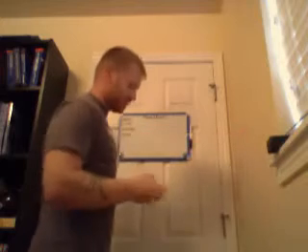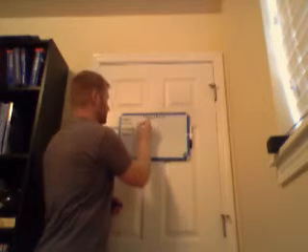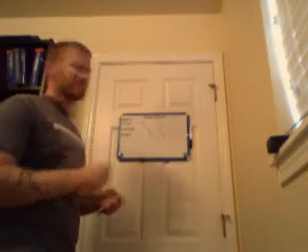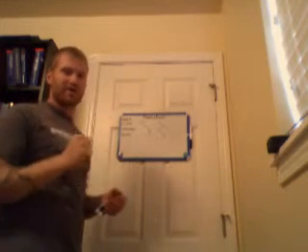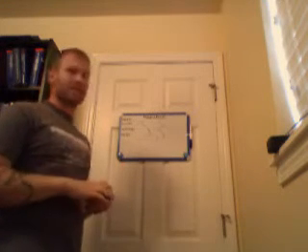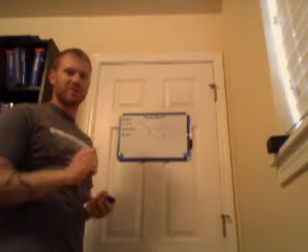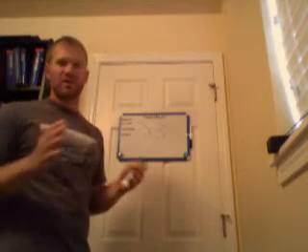And if you have too much forward CG, it looks something like this. Same thing. Basically, your controls are limited. You'll be using so much aft cyclic to maintain a level attitude that you might not have enough left to slow your approach, or in case of an auto rotation, you'll be hard pressed to get enough aft cyclic to produce a good flare and build those RPMs. So basically, what we want to do is stay well within those CG limits.